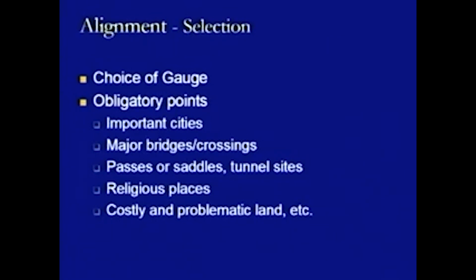So, therefore, in this case it is better to omit this type of land, and this land can be used for other development purposes through which revenue can be generated in different forms, whereas the alignment of a railway can be provided very adjacent to this land, where the land value is not as high as it is when you have to pass through it in the case of a shortest alignment.